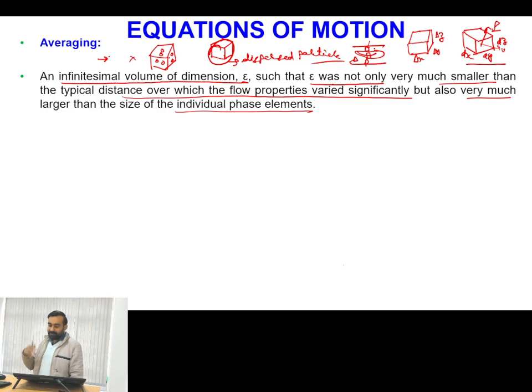What we actually do is try to adapt certain ways, because while defining these equations, based on the volume fraction we will be defining some mixture properties. So automatically, if here and here the volume fraction of one particular phase becomes 0, then the mixture property itself will take the properties of the single phase. Have you understood? The equation will be the same, but depending upon the volume fraction, its mixture properties will change. So accordingly it will adjust depending upon the nature of the volume fraction present. Is this point clear?